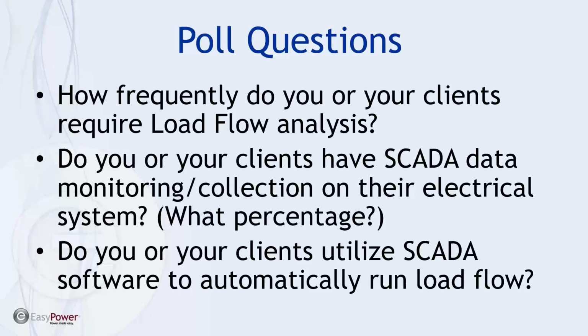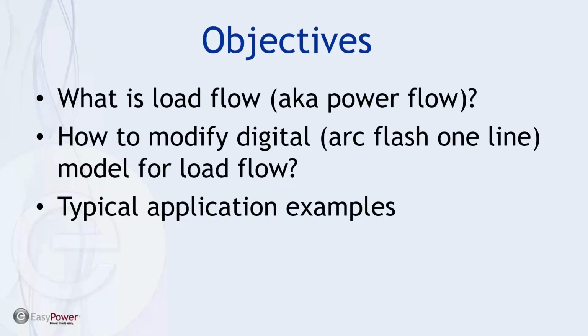All right. So the objectives today is to talk a little bit about what load flow is, not making an exhaustive examination or even an exhaustive demonstration. I do want to emphasize how to modify the digital model, which is a one-line diagram that was used for arc flash, because there's a lot of value that can be extracted from that with relatively little additional effort. And then talk about a couple of typical examples.